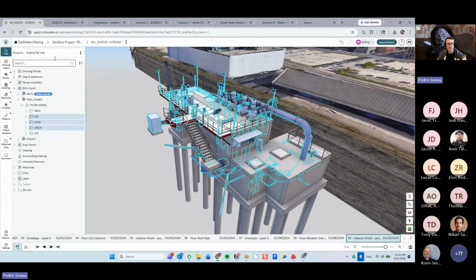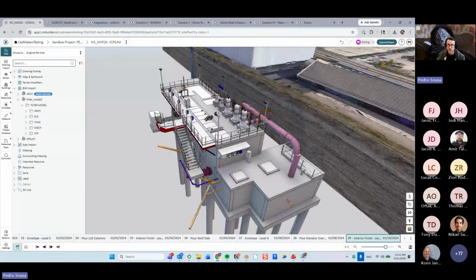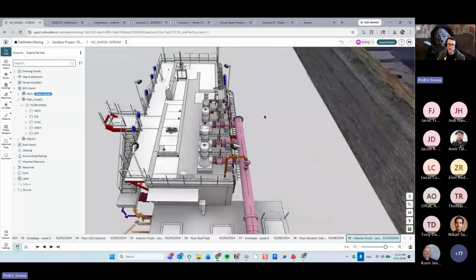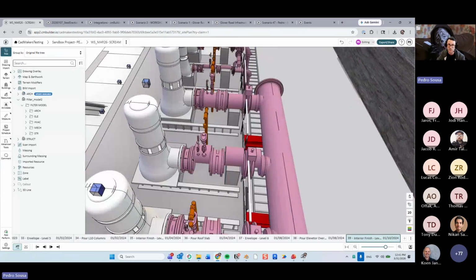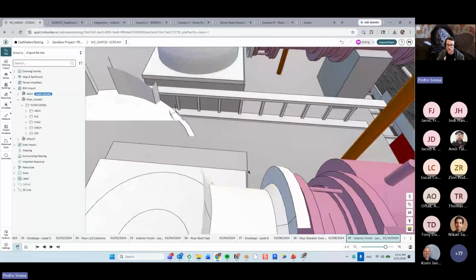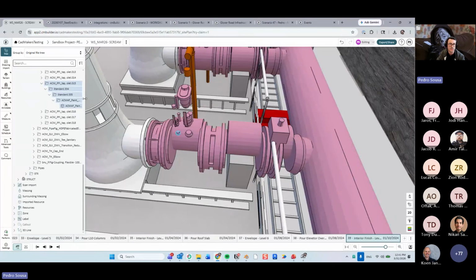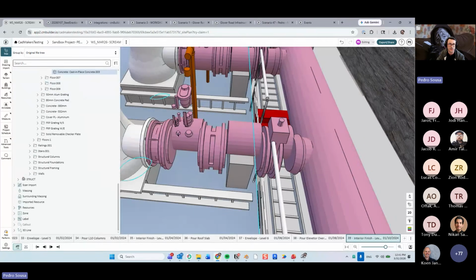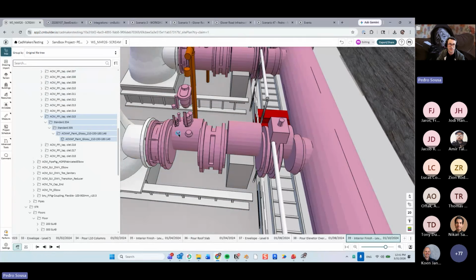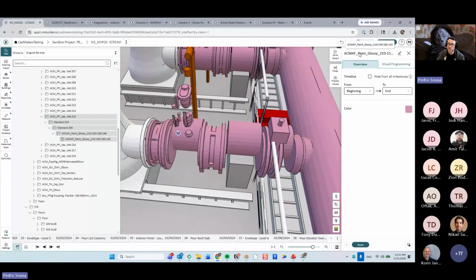So these two grouping methods, you can navigate between them depending on the model that you're working with, if it's an IFC Revit file or if it's a Navisworks FBX, okay? So you can also use other things to help you select these elements. For example, if I click on one of these elements that I want to remove, let's say one of these fittings over here, I can click on this object and I will see the name of that object on my tree structure, or if I double click it, it will show up over here on the top.